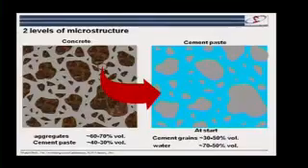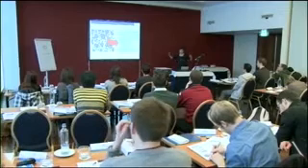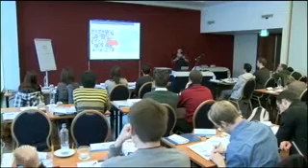So at this second level of microstructure, this is the micron level, these are now cement grains, and at the start, the gaps between them are filled up with water. And that's very important because the whole property we have of concrete, that it's fluid and we can put it into all different shapes, depends on the fact that we have enough water here to keep those cement grains apart and allow them to move relative to each other.